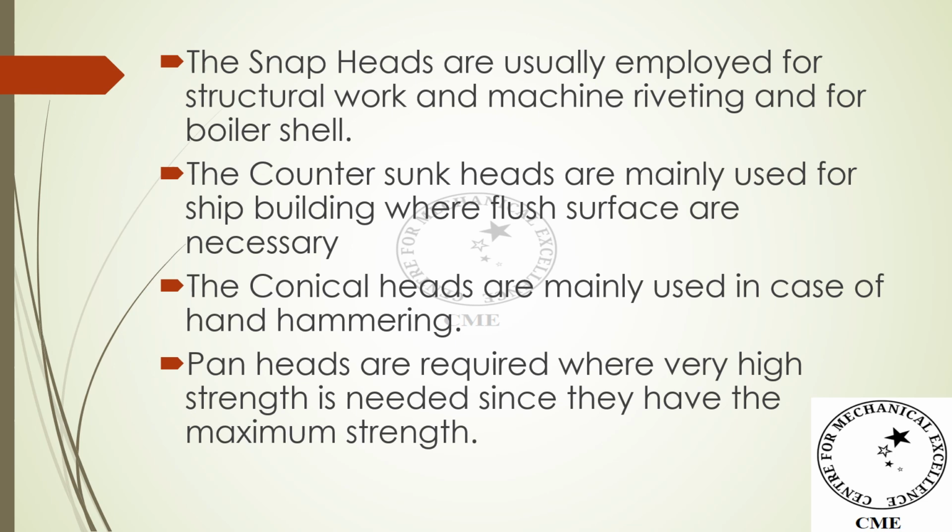Snap heads are usually employed for structural work, machine riveting, and for boiler shell. Most of the time the question comes for the boiler shell: which type of head is used there? That is the snap head. Countersunk heads are mainly used for shipbuilding, where flush surfaces are necessary.